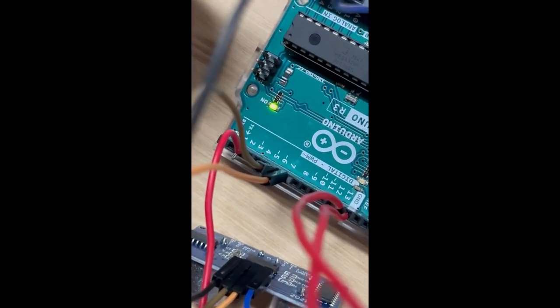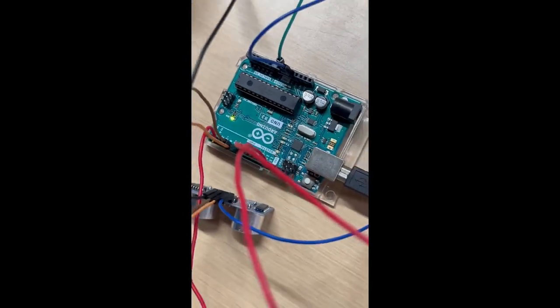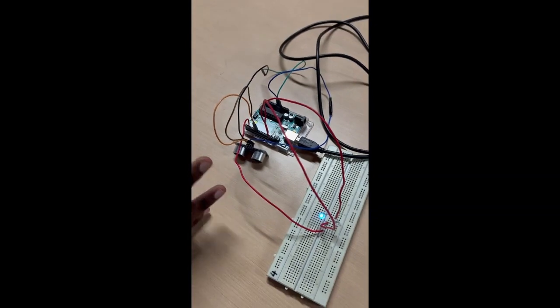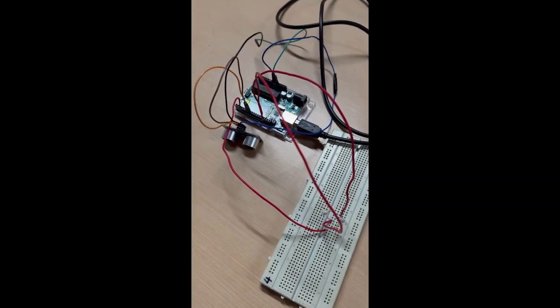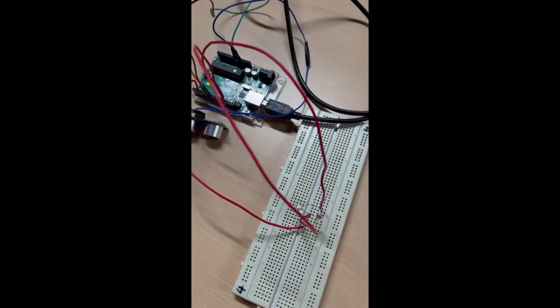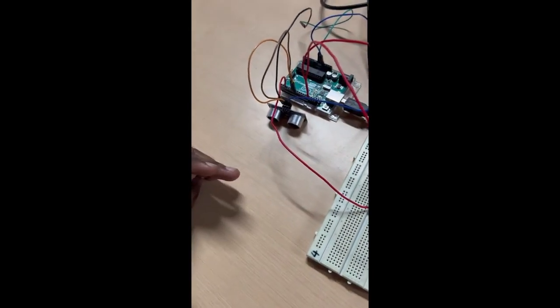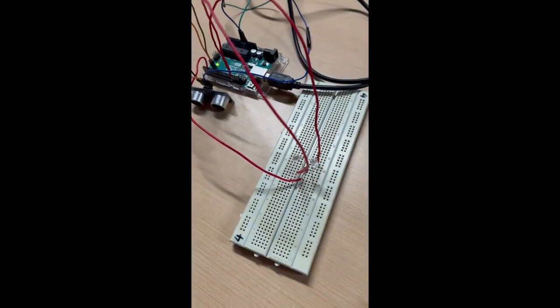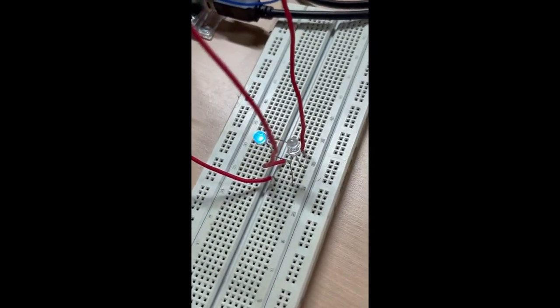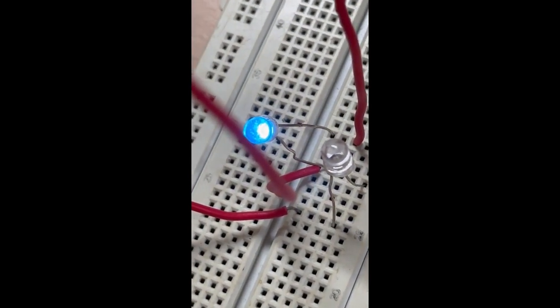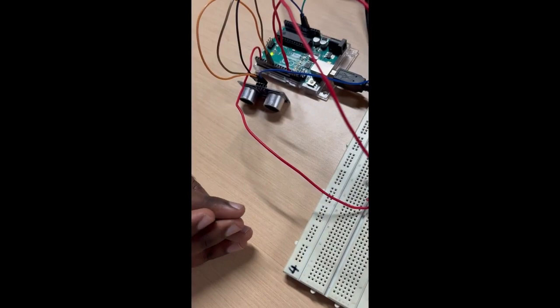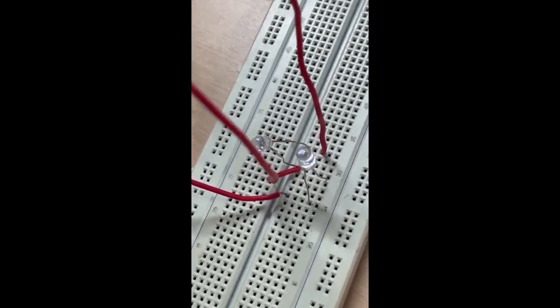The Arduino has been loaded with a C program which measures the distance of the object in front of the sensor. So this will be implemented on the back side of a vehicle, so it can measure the distance to the vehicle behind the car. Once the distance is less than 20, and this 20 can be scaled up to real world measurements, for now it's a small prototype, that is why we are setting the distance as just 20 centimeters. Once it detects that it is in the range of 20, it will signal a collision warning.